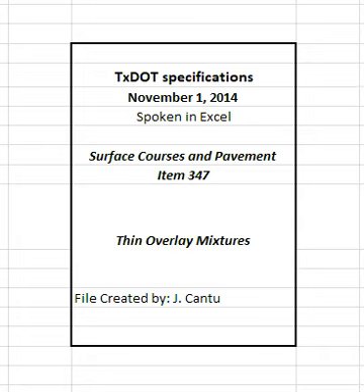4.4.1.1 Target laboratory molded density when the TGC is used. Design the mixture at a 97.5% target laboratory molded density or as noted in Table 7. 4.4.1.2 Design number of gyrations, Ndesign, when the SGC is used. Design the mixture at 50 gyrations, Ndesign. Use a target laboratory molded density of 96% to design the mixture, however, adjustments can be made to the end design value as noted in Table 7. The end design level may be reduced to no less than 35 gyrations at the contractor's discretion.